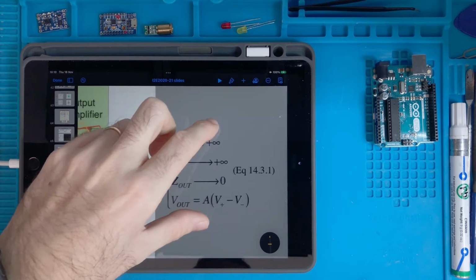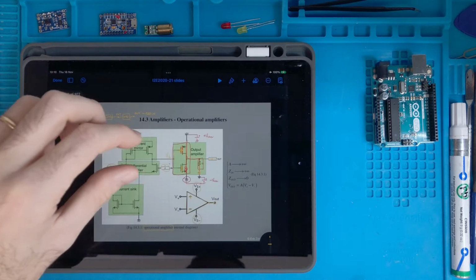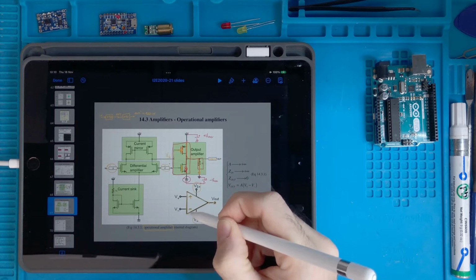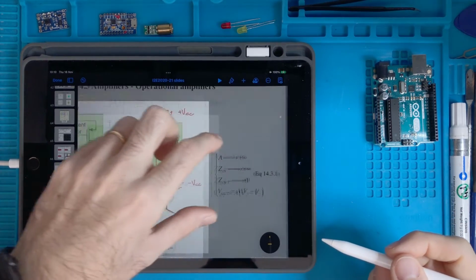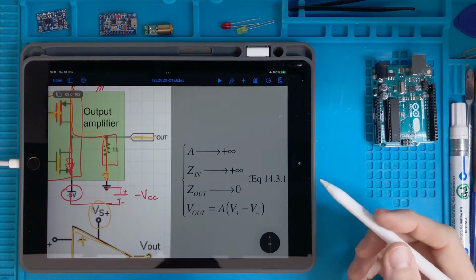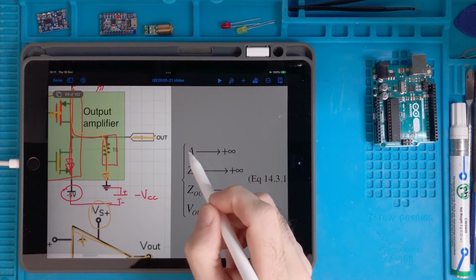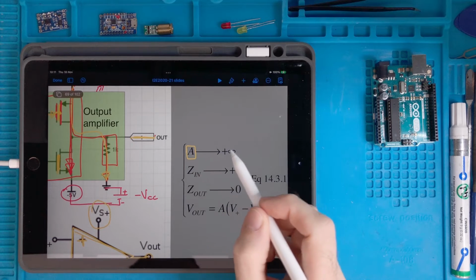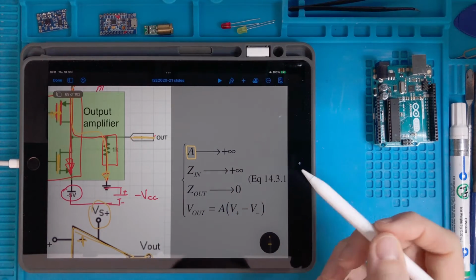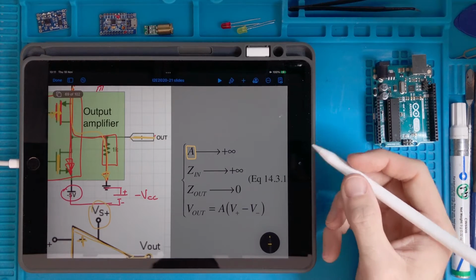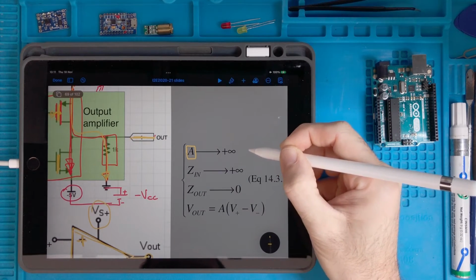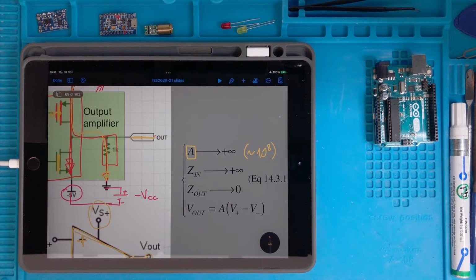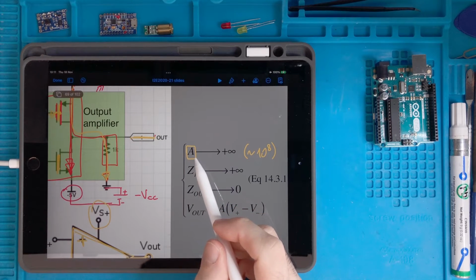So ideally, an ideal amplifier, operational amplifier, is done in a way that inside it has circuits similar to these ones, say inside this triangular symbol, providing us such kind of characteristics. The amplification factor is pushed to, let's say, the limit of infinity. Of course, it's not possible. Usually this coefficient is something like 10 to the power of 8. In the ideal case, it would be infinity.